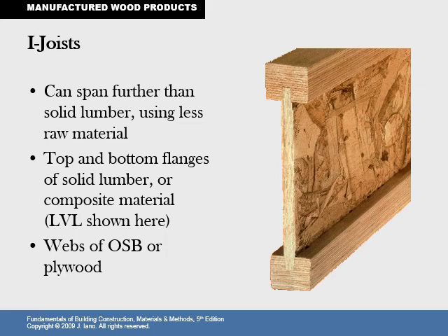The famous I-joist, and you can see its side profile, which is where it gets its name, can span further than solid lumber using less raw material. Top and bottom flanges of solid lumber or composite material, LVL here. Webs of OSB or plywood, and you have to be careful if you're going to drill into the integrity of this particular beam.